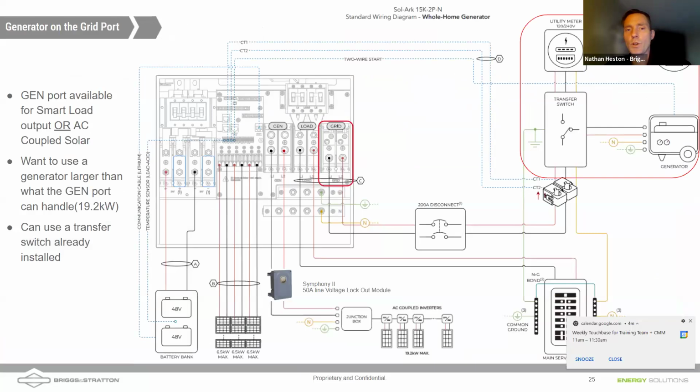If the AC coupled solar is higher than the loads in the house, the battery would already be in a charging state and shouldn't be telling the generator to come on because it's getting low. However, I do realize that clouds can come over and then go away. And so you might have a small amount of AC coupled solar because you've got cloud cover. Your generator's running and charging your battery, and all of a sudden the clouds move, and your micro inverters come back on, cover the loads of the house, and potentially backfeed your generator.